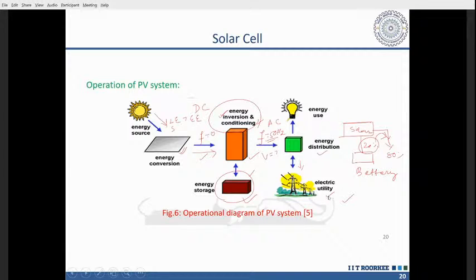Wherever we are interested. Again, from the energy conversion process, you can also send this DC energy to the energy storage system. You have a battery connection near your inverter system. Before the DC from the output terminal of my solar panel enters the inverter, I will tap the DC energy to a battery. When required, it will charge the battery. And when the solar system is absent, the battery will discharge the power through the inverter, and the inverter will supply the power to the AC loads.